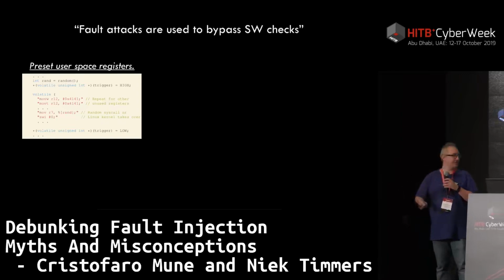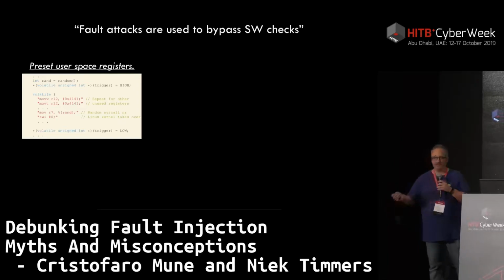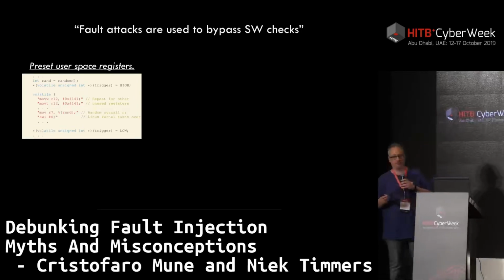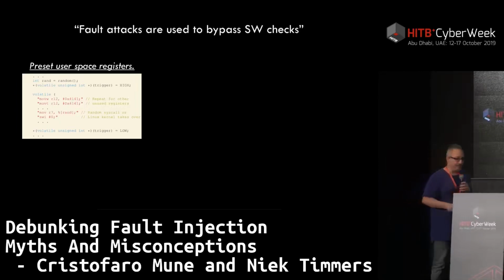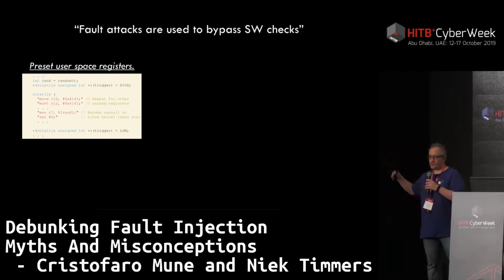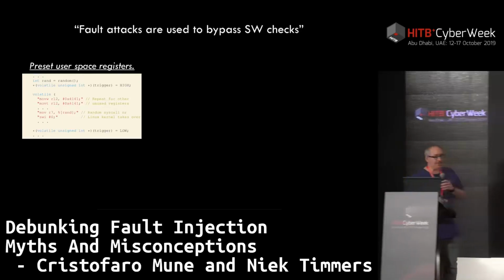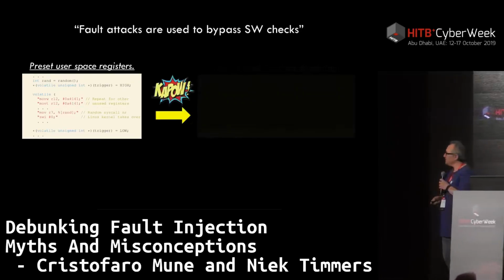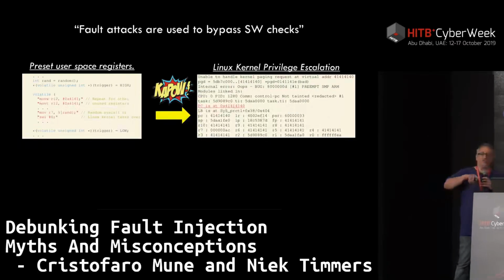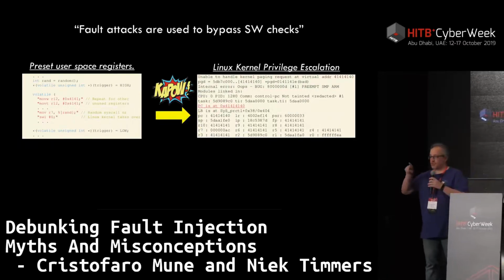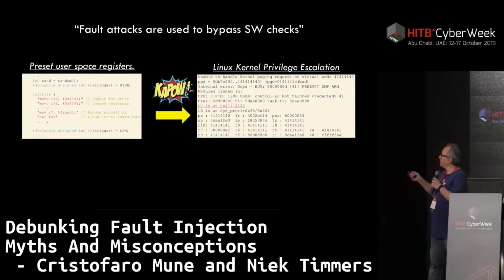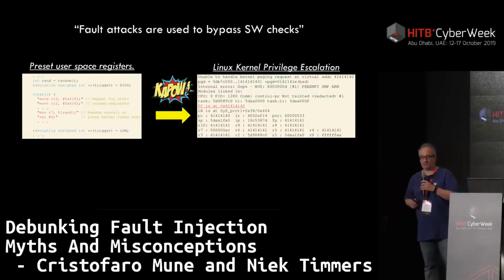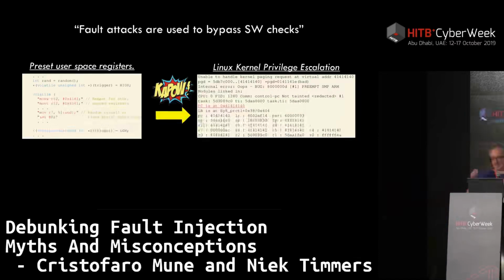So if you're doing, let's say, voltage glitching, you will lower your voltage enough to inject some fault. If you're doing clock fault injection, then you will vary the clock within the time. EM, you will just provide a difference in EM field and inject a glitch over there, laser, same stuff. So whatever you need to do needs to happen within that point in time. And chances are that in some architectures, this may be easier than others, your syscall is performed, but you are shooting and you are causing one of those addresses to enter the program counter. And you see here in the picture that PC, which is the kernel program counter, is now set exactly at the value that you wanted.